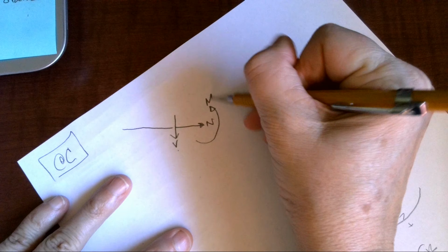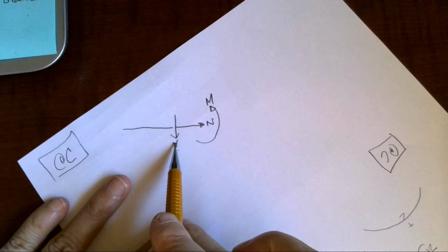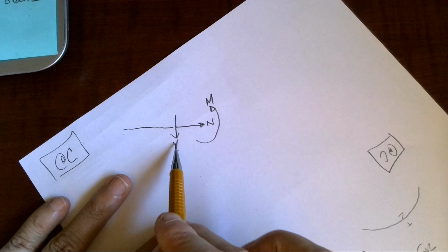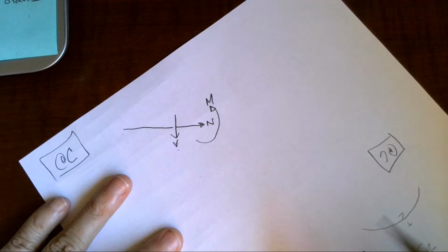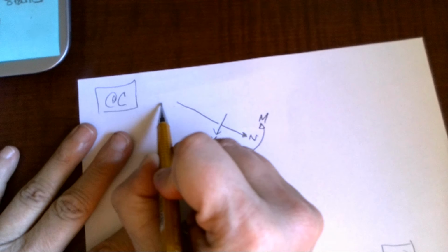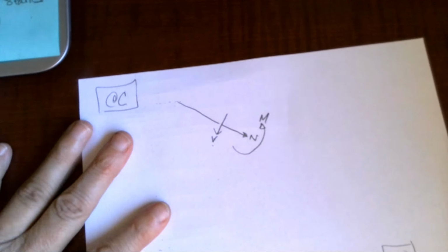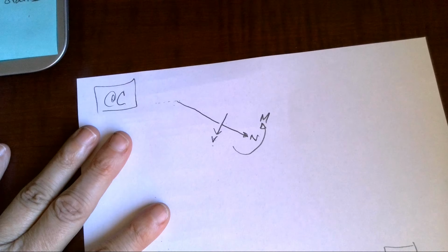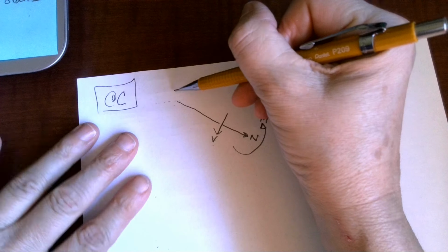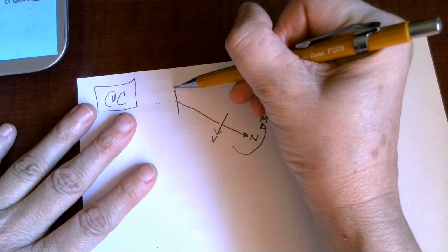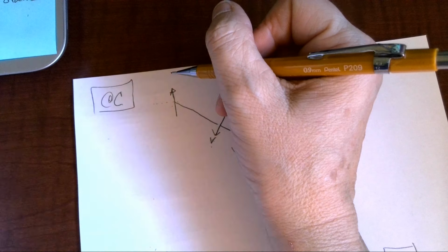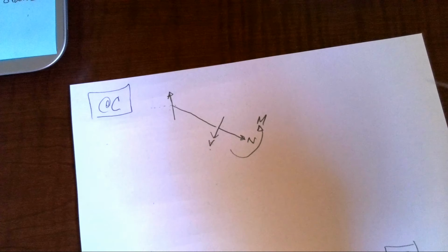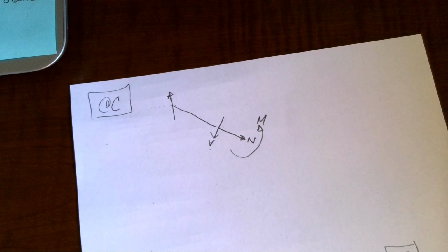We are coming from left to right, so I am showing you positive notation: clockwise rotation, tension, smiley face curvature. When I come back to my reaction, I note that I don't have an X component. If I did, I would just have to make sure I dealt with that. But I do have a Y component, and my Y component is, sorry, I have to go back and look, 3.52. Yep, 3.52 kilonewtons.